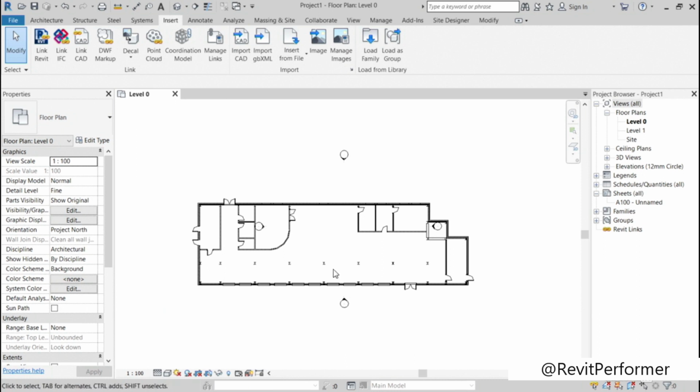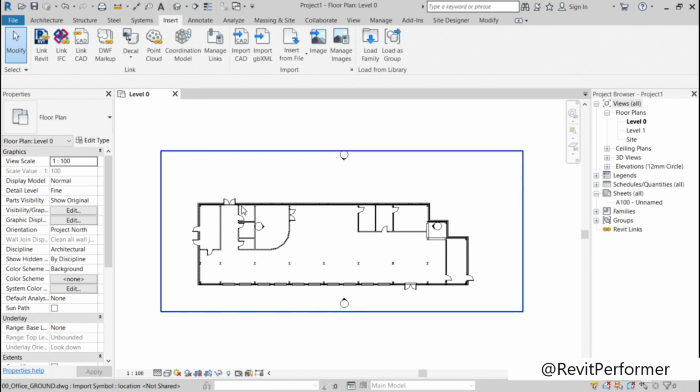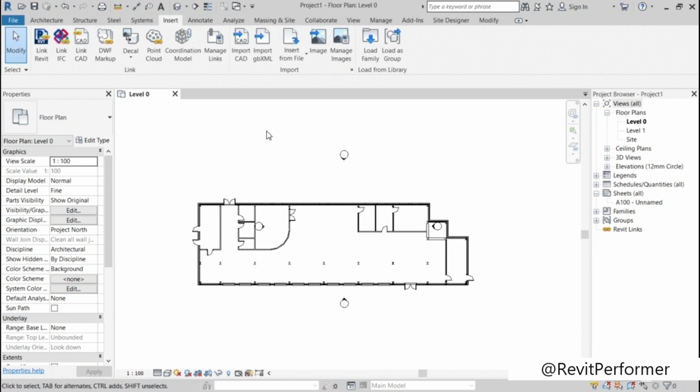And you don't want to keep snapping to intersections of grids and things. The only time you really need that is when you're placing things like columns. So once those columns are placed and the grid lines are placed, and you want to start adding walls, then you can start adding walls based on the linked CAD file here, you can kind of switch things on and off. That's the benefit of the visibility.